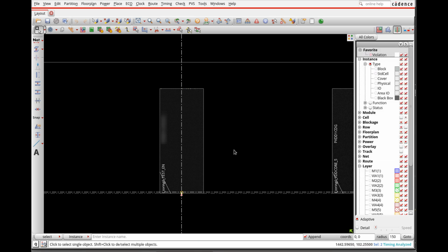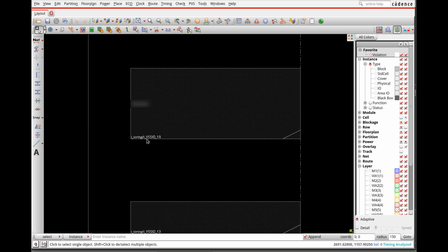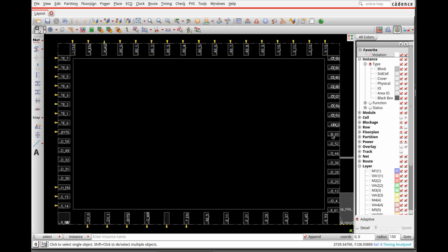So that is a pin for the design. But I see that all of these yellow things are here around these 3 sides, and that these guys don't have any pins on them. So if I zoom in and look at what these are, I see that this is a VSS IO. In fact, all of the power was put here on the right side. That is not great. So I see that my corners here are all in one place. There are no corners in the corner.